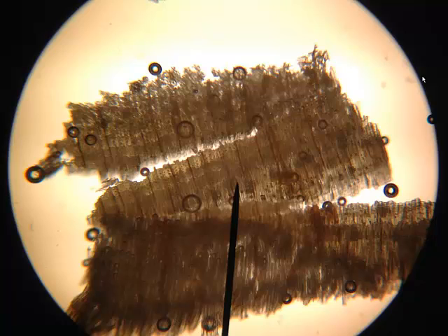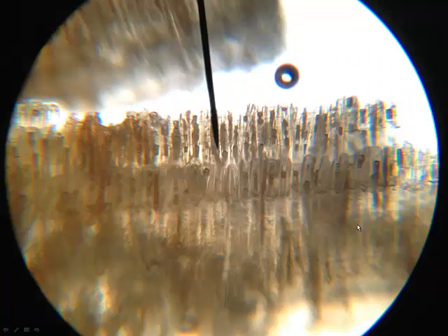What I want to call your attention to is the cellular structure that we see in the wood. And notice these dark areas and light areas. To understand what that is, I'm going to magnify this, and we're going to go to 80 times magnification. Here we're looking at the cellular structure of the wood, and you're looking at the cavities inside of the cells that comprise the wood. The reason why you see darker and lighter areas inside of these cavities is that you've got water and air both inside these cavities. And just like this bubble we see up here on the screen, you can see the air bubbles that are trapped within these cell cavities.